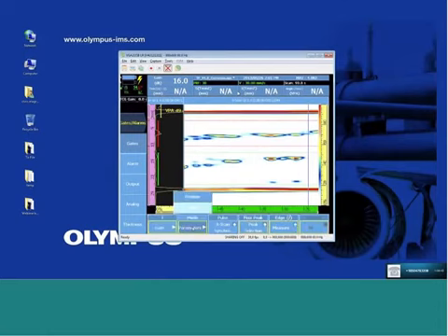normally the mode is in an A-scan synchro or pulse. In this mode, the yellow gate is visible and it's positioned over the interface signal. If I change this to synchronization on I gate, it means that the A-scan 0 position here is automatically dynamically adjusted to the crossing position of the gate.